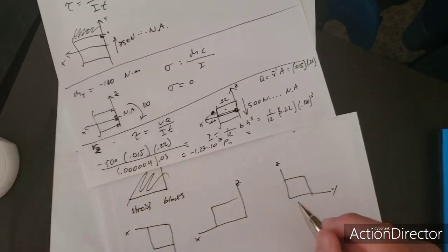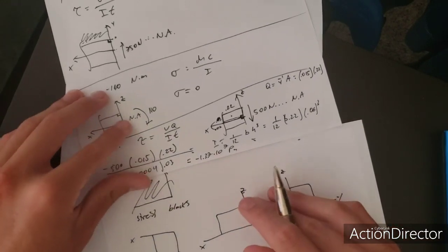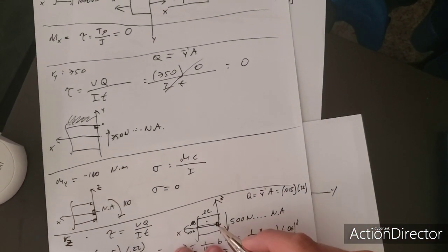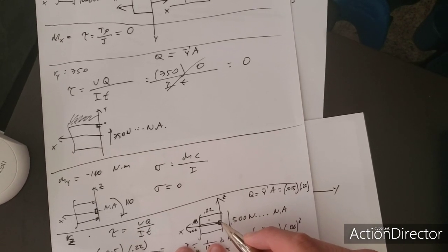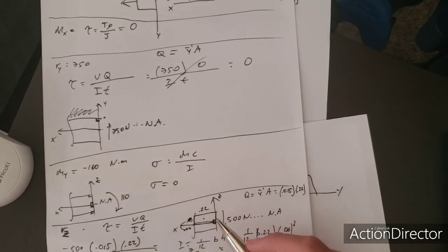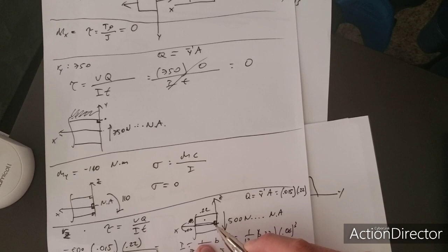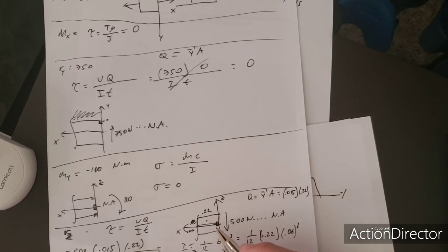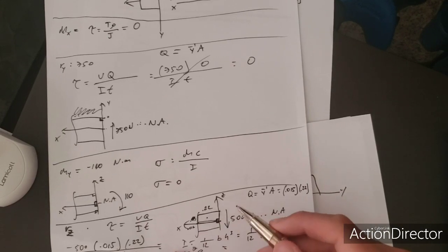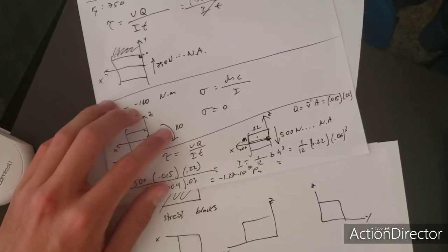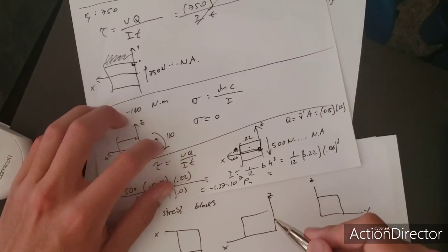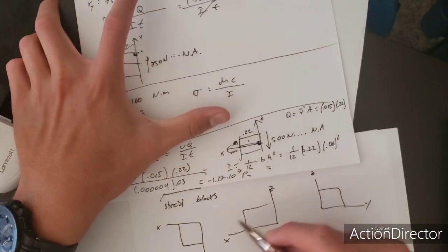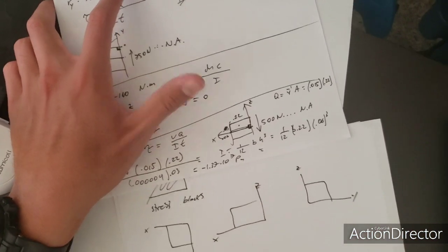So I get a negative, and here the tricky part is, it's only acting in this plane, because this infinitesimally small point, think of it as a little square, is acting on this surface of the xz plane. So the only way this shear stress can go is in this stress block.